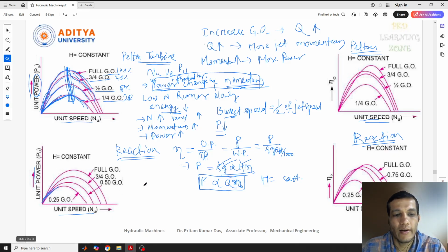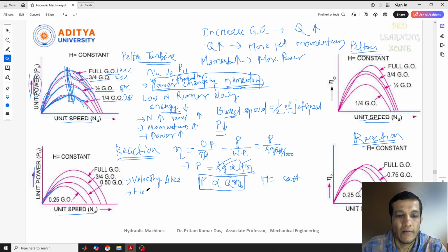So here we get velocity triangles. We have the velocity triangle of the jet at the inlet. The velocity triangles are not properly formed, or you can say it's not optimal. Because these velocity triangles are not optimal, flow separation will start in the initial conditions.